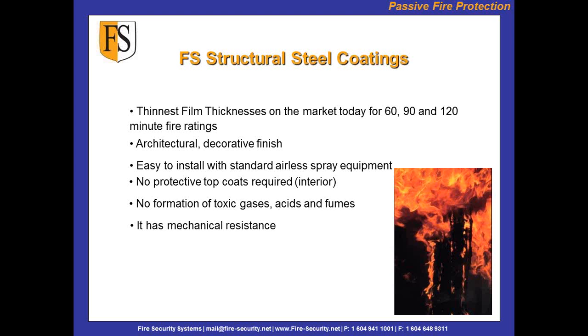Pretty much, because you don't want to stop the fireproofing from fully curing. If you put a coating over the top, you can trap it, and you don't want to trap it, especially with solvent-based coatings. And how do you establish when it's fully cured? Well, you can do a hammer test, but usually by 30 days it has reached its full cure zone.